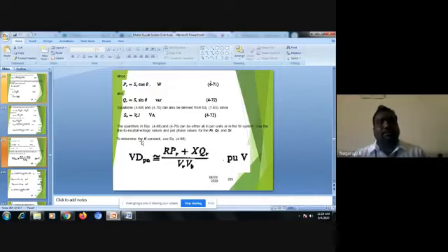Qr is the reactive power with respect to the receiving end. So theta is the power factor angle. Those things I am substituting. Active power you will measure in watts, reactive power in VAR, and finally Sr is equal to the square root of Pr square plus Qr square. That is nothing but Vr into I.